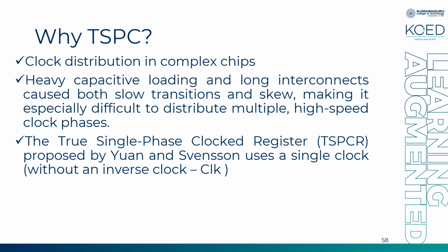And whenever you use more number of phases, the wires will increase, that is, interconnections will go on increasing. So lengthy interconnects as well as more number of interconnects will result in parasitic RLC. Each and every wire has its own associated capacitance. They are conductors, they will have their own capacitance. So all these will change the working of my circuit.